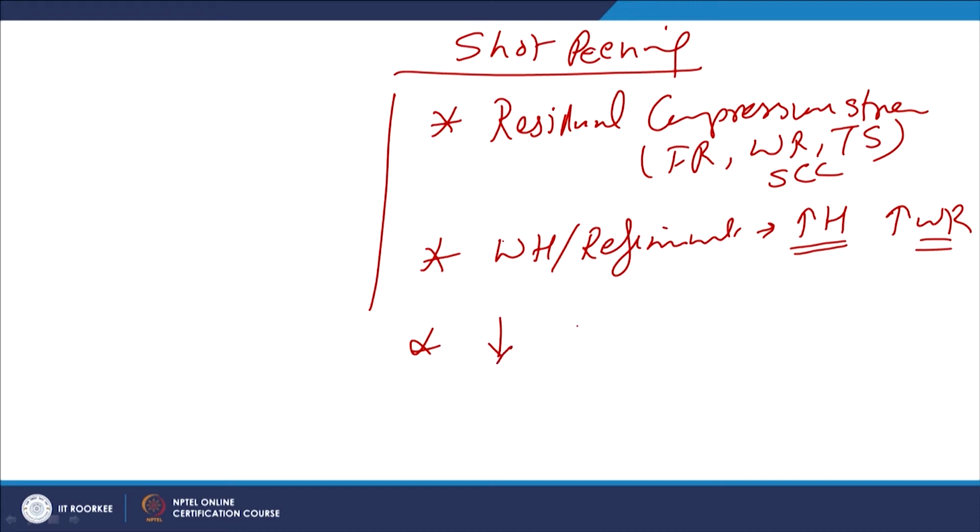with regard to the development of cracks if the material has limited ductility and is subjected to severe shot peening. These cracks can cause premature fracture if they are not taken care of properly, and there can be another unfavorable situation where the surface may get roughened.